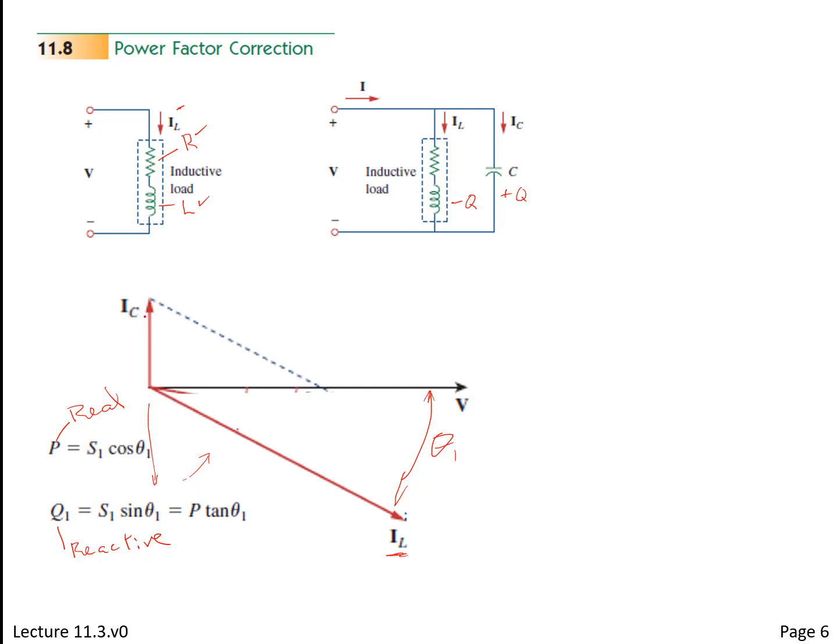The capacitor has no such animal. And this tends to be true. Capacitors, because they're not wound coils or anything made of lots of wire, tend to be free of resistance. So here it sits on the imaginary axis, vertical. Okay, it's just going to draw current, but at plus 90 degrees.